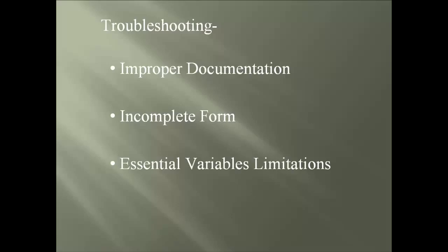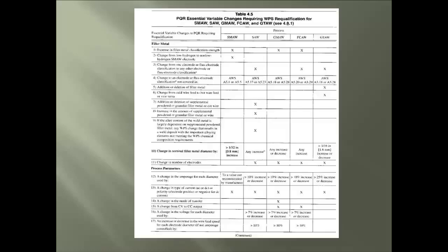And here is a very important table that is new to the 2010 D11 code, which sets the limitations for a PQR that may require the WPS to be requalified. Here we see the new table for the 2010 D11, and there are 3 pages that cover the items dealing with the PQR.